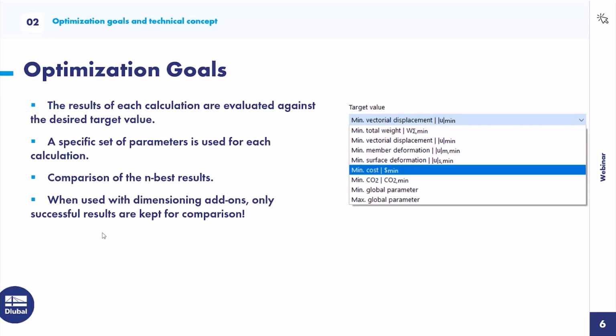And what is very important to know, and really is a strong argument to use this optimization add-on: if you use this optimization together with dimensioning add-ons, like for timber construction, concrete or steel design, or even stress-strain analysis with limits you defined, only successful results are kept for the comparison at the end.